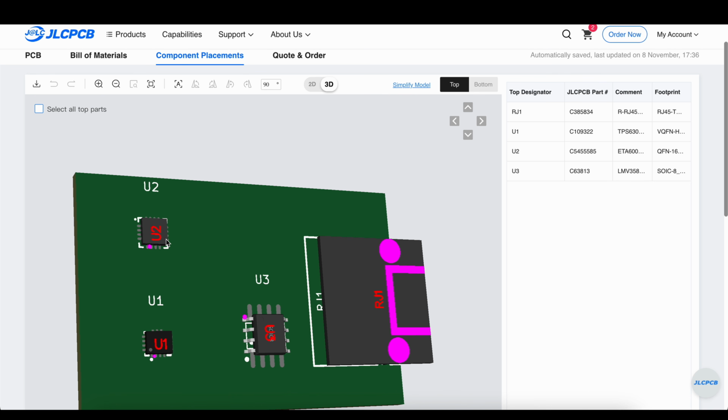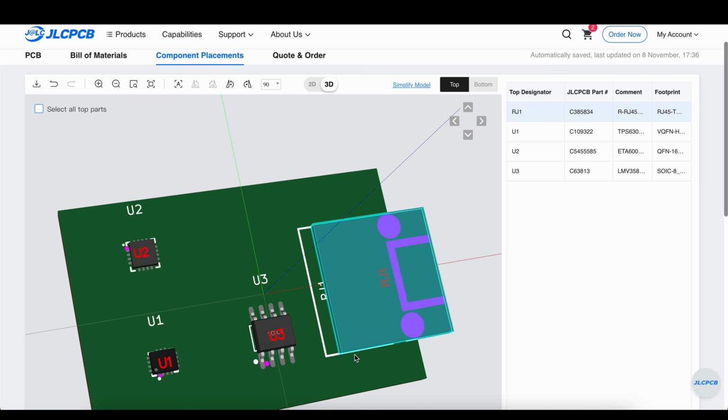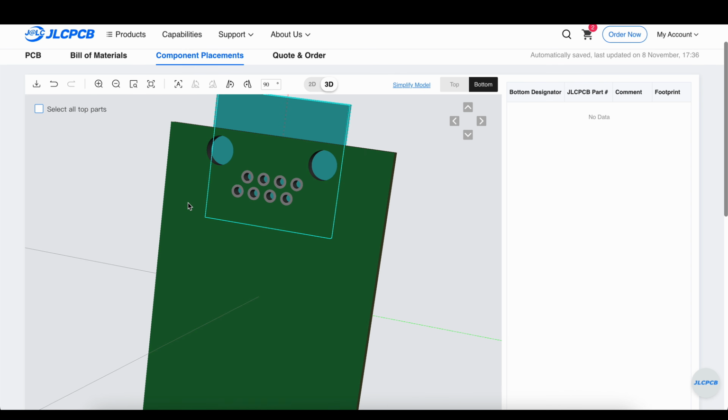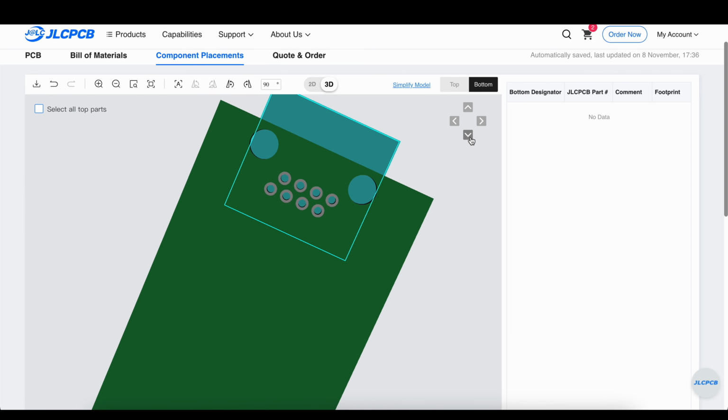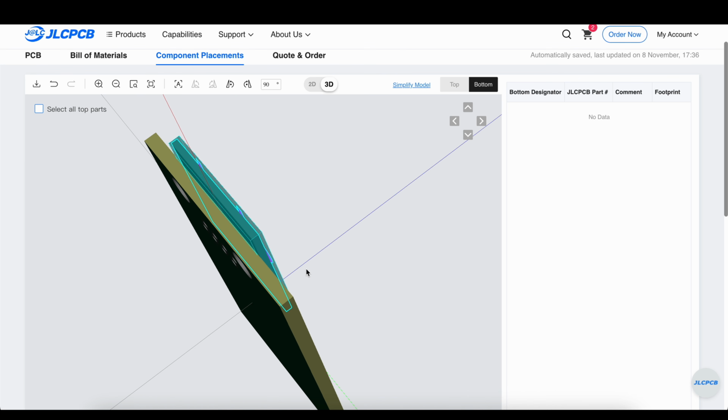And I'll show you how that works. You go like this, you hit the space bar until pin 1 lines up there. You hit the space bar there, pin 1 lines up there. And then we have to go through kind of a manual adjustment process with this one. Let's look at here. I think there's little, yeah, you can see. So I'm doing the little arrows here. Okay, now we can see those pins lining up. Yeah, I'm not sure what happened to this 3D representation. It's not great, but you can see now that we've totally adjusted this thing to be in the right place.